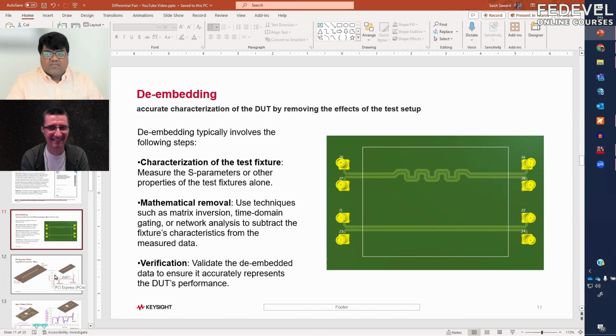Yeah, so I wanted to stress the importance of de-embedding, and you mentioned a good example. Even now the latest thing would be HBM. The HBM memories are getting stacked on top of one another, so measurement challenges for that are a case. You'll see more and more about de-embedding your interposers in the new things that would be coming up.